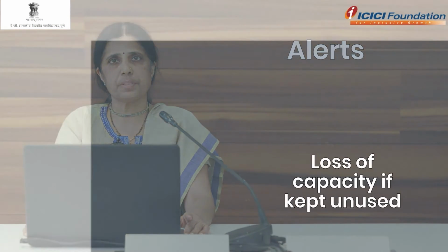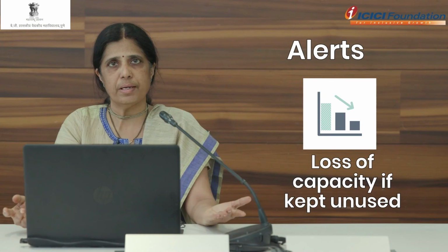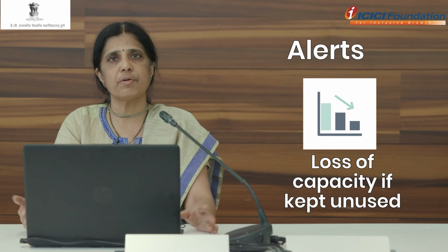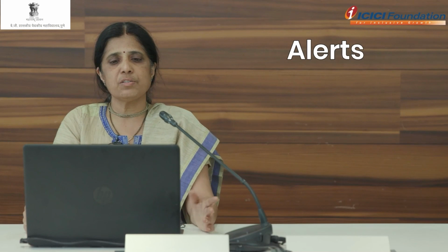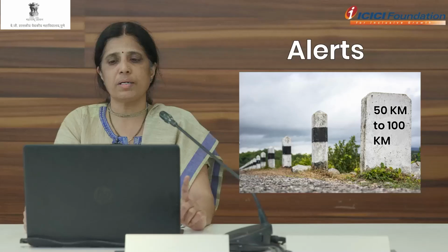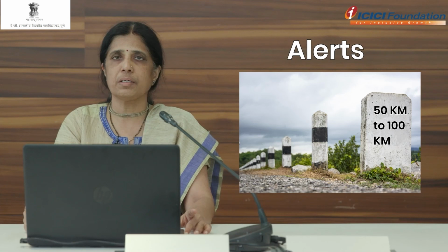If LMO is kept unused and idle for a long period, the gas might vaporize into the atmosphere, causing a lot of oxygen wastage. Presence of a liquid oxygen supplier within a 50 to 100 km range is mandatory because we have to fill the LMO tank quite often on a day-to-day basis.